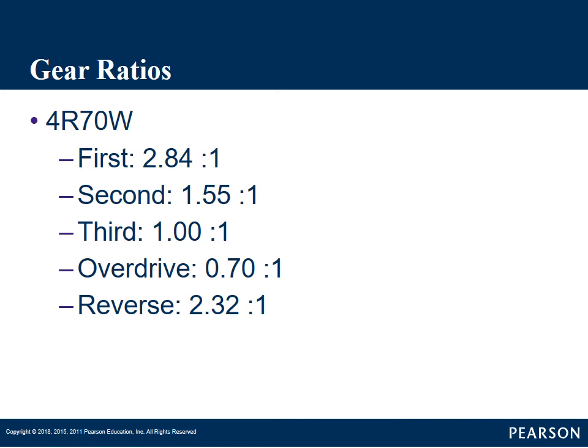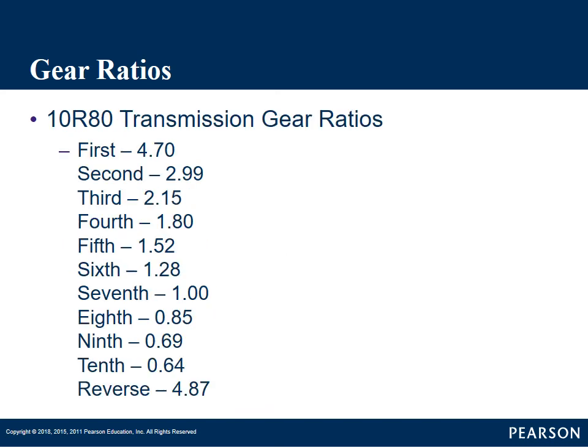Well, the whole idea of our multi-speed transmissions is to try and keep that engine in the optimum RPM range to match the design of the vehicle. For the longest time, up until overdrives, it was 2- and 3-speed transmissions. Then when we added overdrive, it was for the longest time 4 speeds. Then they added a 5th speed and a 6th speed. But now, which is our next example, we have a 10-speed. And this is Ford's 10R80.